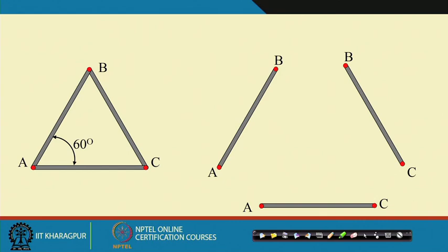You can have n number of members. If it is a plane truss, or a space truss, then the members will be oriented in 3-dimensional space. It depends on the problem we are considering. Okay, so once we have different parts of the structure, the next step, if you recall, is to write an equation for each part. And what is that equation? The equation is the force-displacement equation.